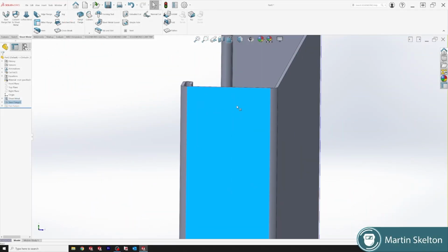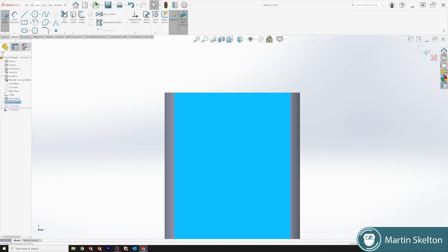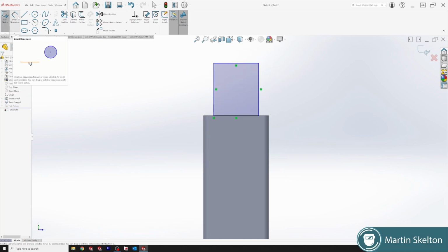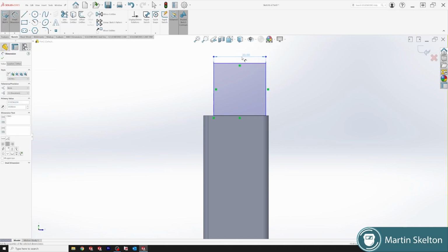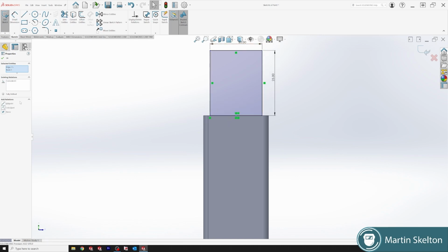So we'll actually use the top here. Click, file, sketch. Click here. Join our tab. We know our tab from our sketch is 20 millimeters. We know it is 25 in length. And we want it centered. So we select the midpoint, hold your shift key, select the midpoint, and then you're making them concurrent.